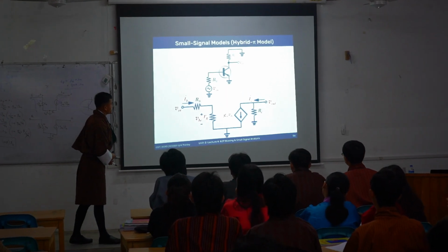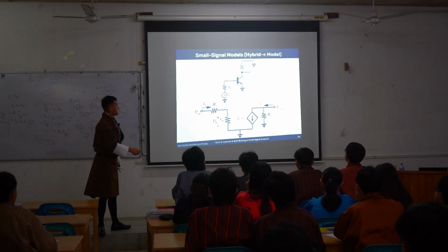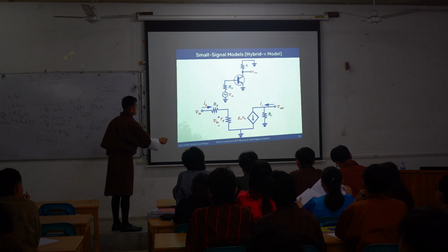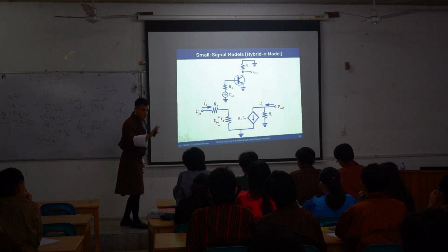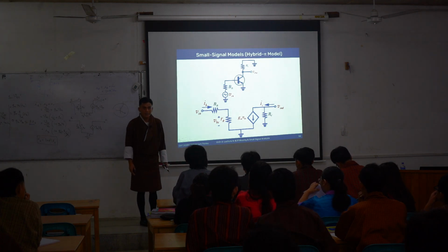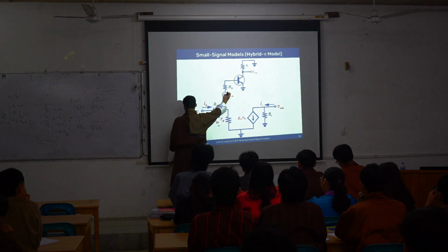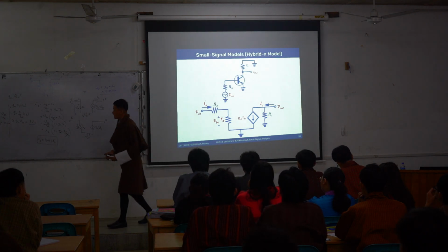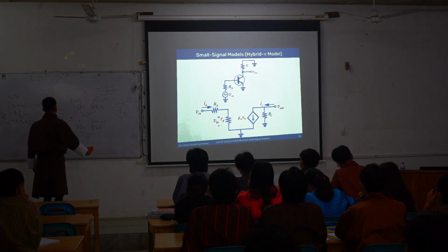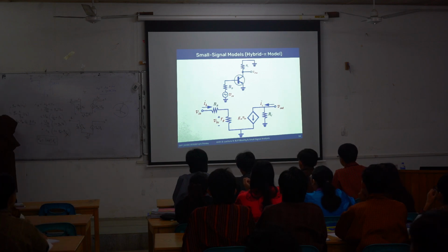Yes, so this is one example of how to represent your circuit, right? If you observe this particular circuit, I'm only representing the AC part. Why? Because all the DC sources are being shorted. I can write the full circuit before the application of your AC source, and it would be similar to this circuit.